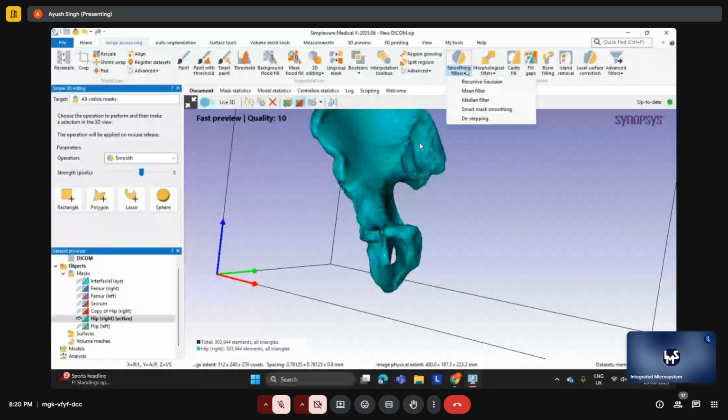Coming back to this particular smoothing filter, we have various options: the recursive Gaussian, then a mean filter, median filter, then smart mask smoothing, and the de-stepping one. For example, if we are working with the recursive Gaussian, we can go over here and select the particular part.